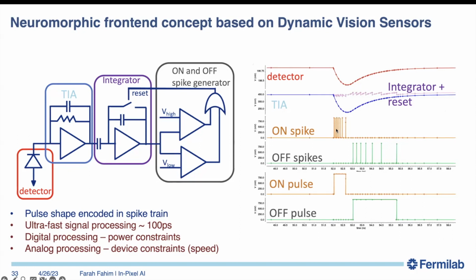Okay, so if I don't do this, and instead modulate the pulse width that is generated, all of these on spikes correspond to a single pulse, and the off spikes correspond to another large pulse. But instead of it being a digital pulse, now it's a semi-analog pulse, because the width of the pulse matters, and not just the number of pulses. That is an analog neuromorphic technique, which we are thinking of exploiting, just so that we can get the best of the two worlds.